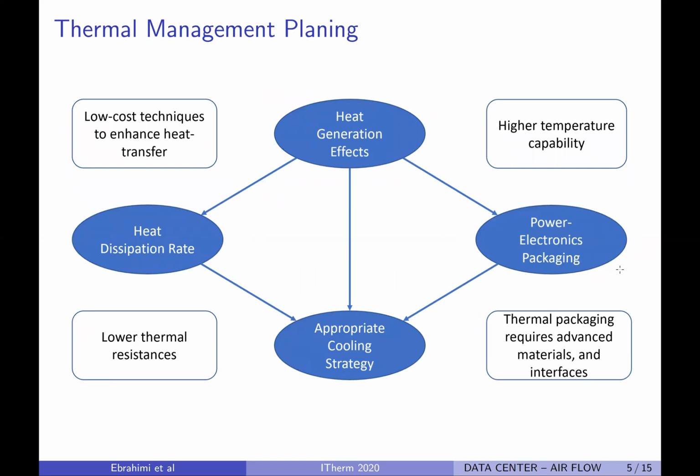For thermal management system design, we need to consider a few factors. We need to have a correct understanding of peak heat dissipation rate, the location of heat sources, and the system size and cost. Considering these factors, we make the decision whether to design a passive or active cooling system. We usually aim for a less complex system with higher controllability and good dynamic system response. With the implementation of advanced thermal interface material, it is possible to design heatsinks with high cooling efficiencies.